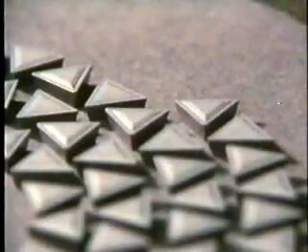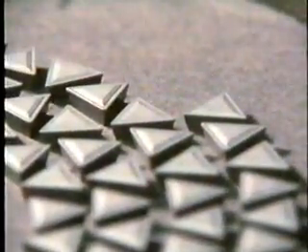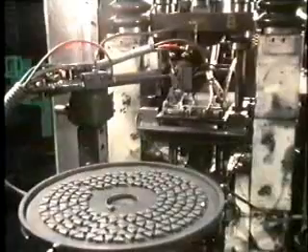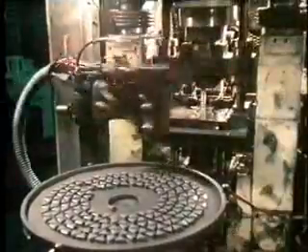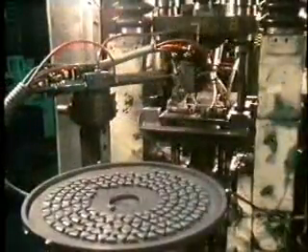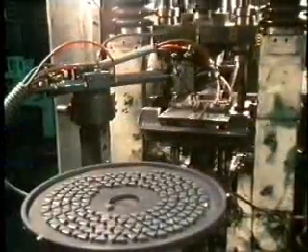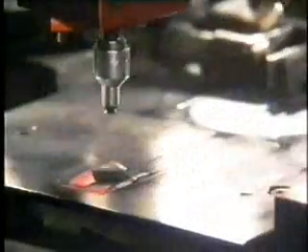The inserts are produced by powder metallurgy, similar to the process used with powdered high-speed steel. Tungsten carbide is milled to a fine powder and mixed in the desired quantities with powdered cobalt. This mixture is placed in a mold and pressed to form a slug. As the inserts are friable at this stage, they're handled with specially designed and very sensitive equipment.